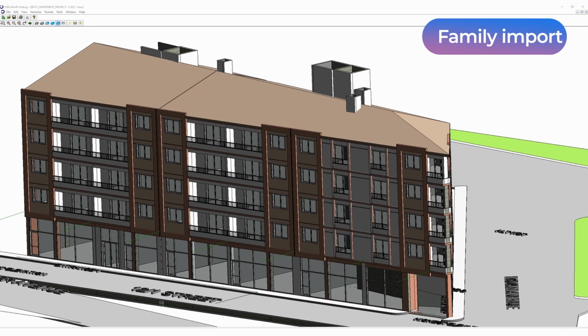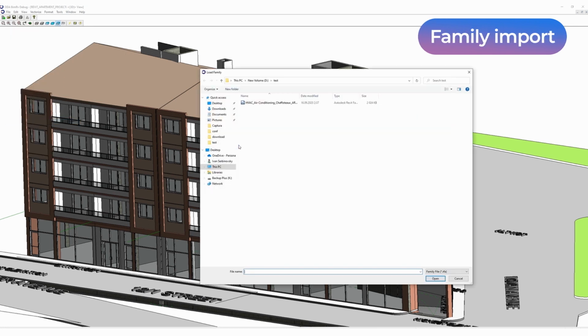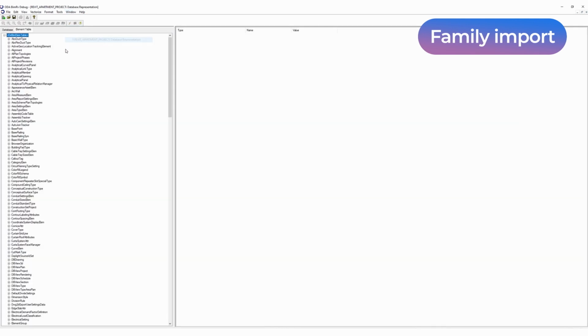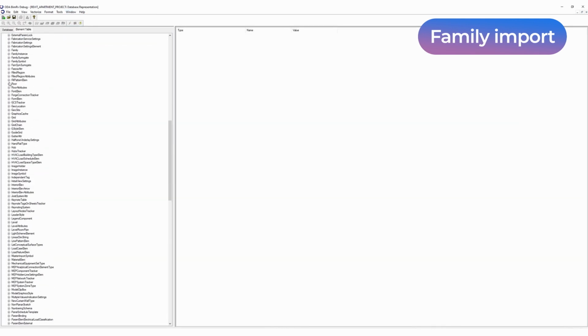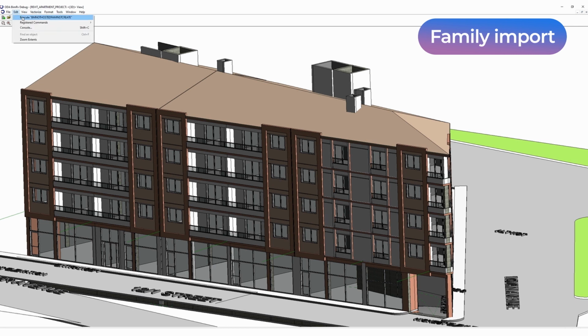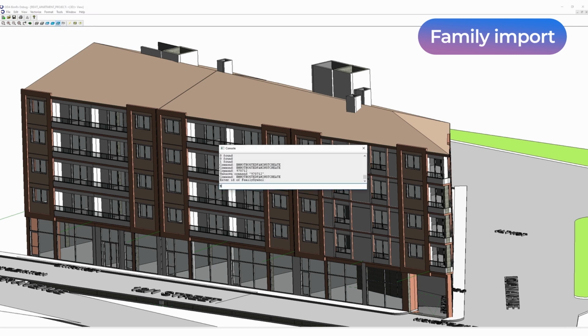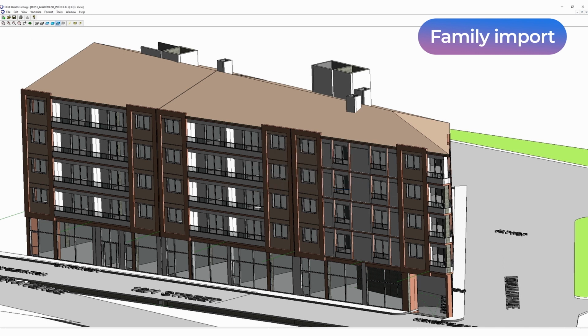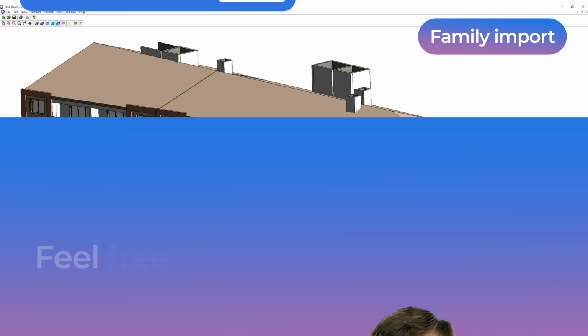For import families, we can import a family into a model or family database and create an internal family database. Create new family symbols during import. Activate family symbols if we can rebuild the geometry of the family. During activation, we need to create the geometry of the symbol. And finally, we can create new family instances for activated symbols. Creating new instances for hosted families also requires modification of the geometry of the host element.